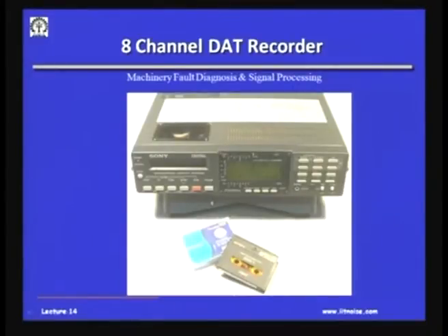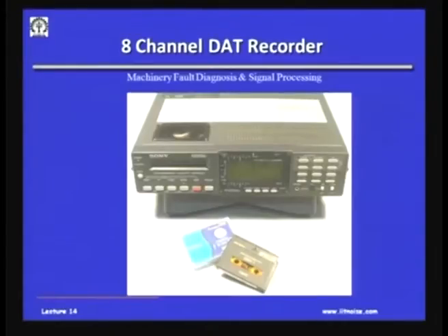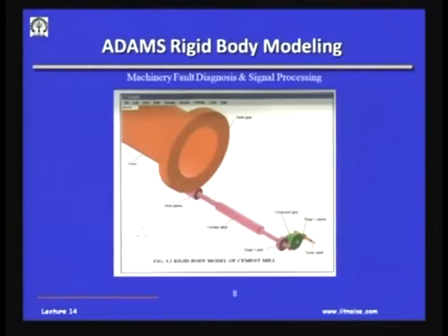You can record them on the tape, because in such a dusty environment, with cement dust everywhere if you go to that plant, we cannot be putting computers and sophisticated equipment and doing an analysis in an area of cement dust. So, all you do is record them on that media, bring them to the lab, and then use your software, MATLAB. You can do FFT, and then do this Cepstrum analysis as per the algorithm I just mentioned.